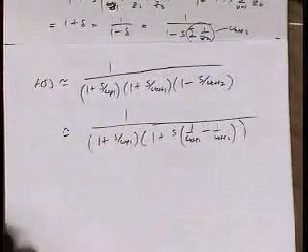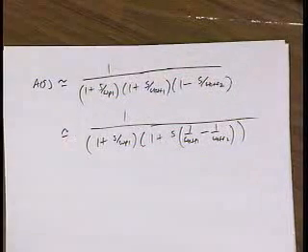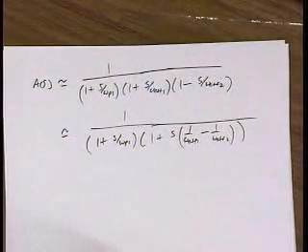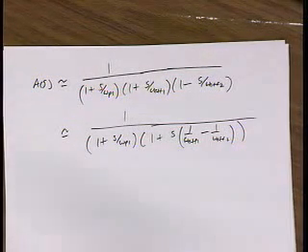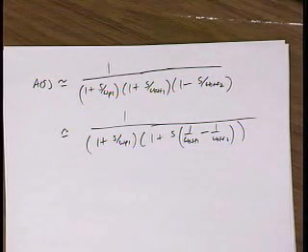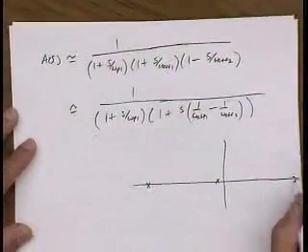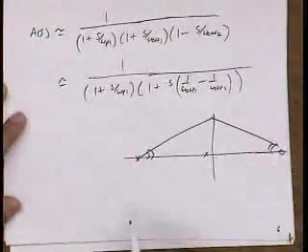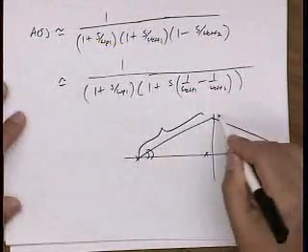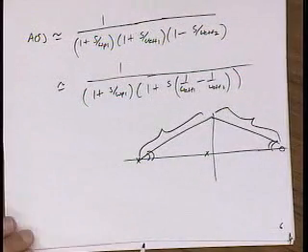And that kind of justifies the graphical picture that I drew earlier. Okay, questions? Yeah, excuse me. Is it possible that the second terms kind of cancel out the first omega p? Yeah, that's what we found when pole zeros canceled, right? If they're about the same magnitude, they cancel each other out. On this picture, if I have a pole here and a zero exactly at the same location, they contribute the same angle, and they contribute the same magnitude, and so they do cancel each other out.